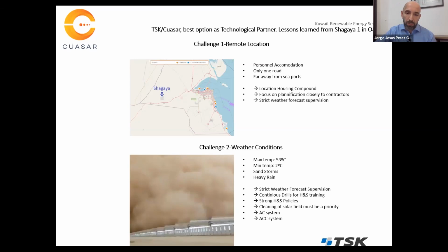Also, you know, a power plant is something that is working with instruments, and you need to keep all these instruments working and supervising closely in order to avoid that this extreme weather condition is affecting their working conditions. And the ACC system is working with air. Yeah, but you have to clean it. You have to put an eye on that. You have to check if the dust is affecting the working of some blades and so on.